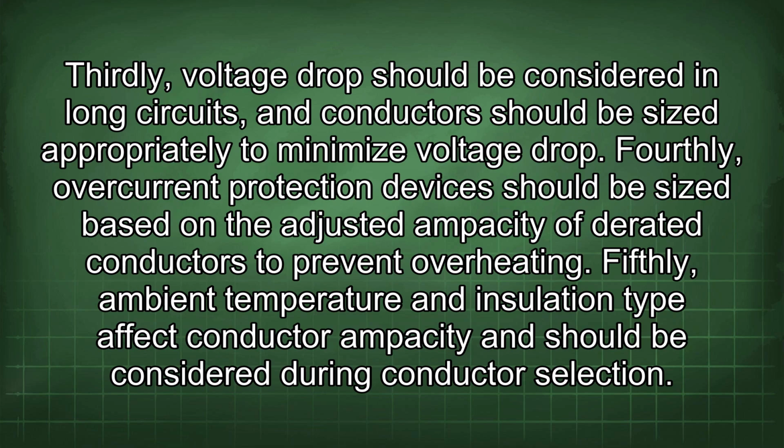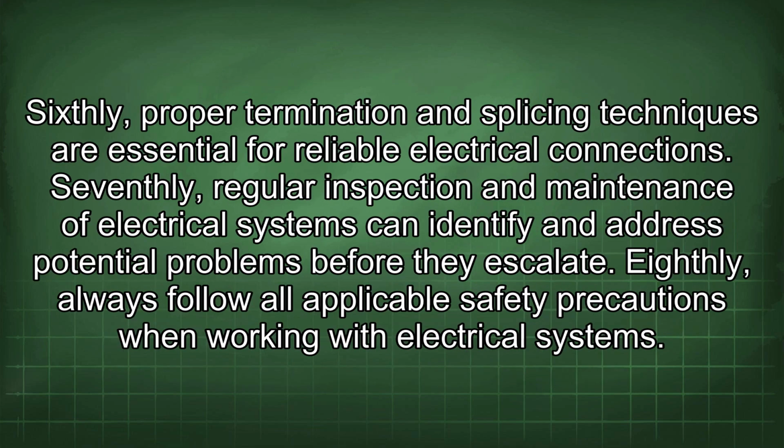Fourthly, overcurrent protection devices should be sized based on the adjusted ampacity of derated conductors to prevent overheating. Fifthly, ambient temperature and insulation type affect conductor ampacity and should be considered during conductor selection. Sixthly, proper termination and splicing techniques are essential for reliable electrical connections. Seventhly, regular inspection and maintenance of electrical systems can identify and address potential problems before they escalate.